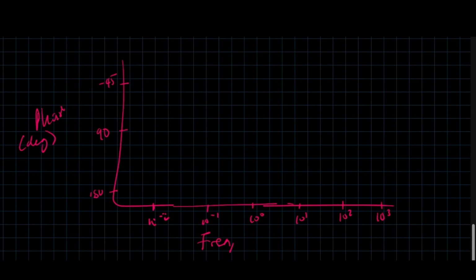Now, the total slope for 0.05, which is somewhere around here, was 45. So remember I told you at the origin all frequencies were minus 90. So it will be negative 90 to get to this point, which is around 0.05. It went up by positive 45, sorry. Then it went up by positive 45 till it reached 1, which is around here.